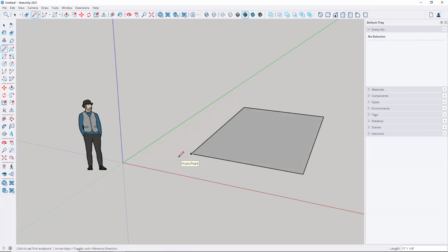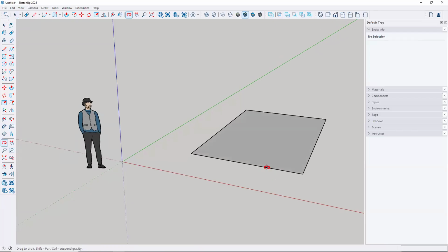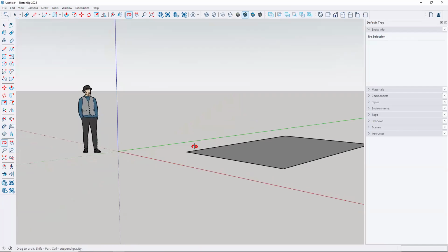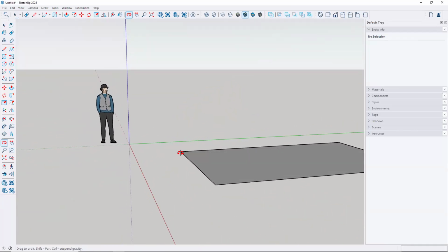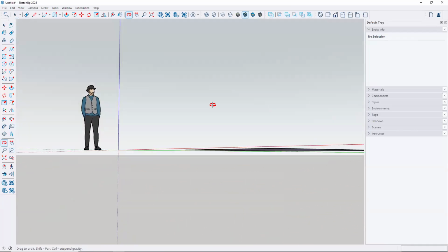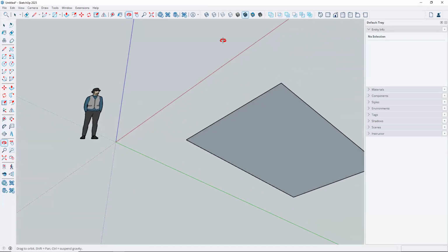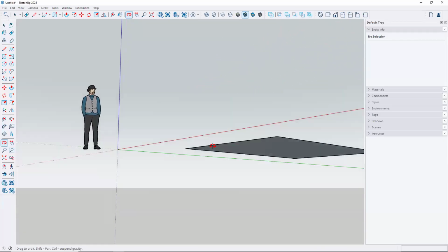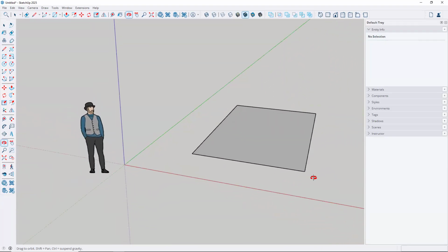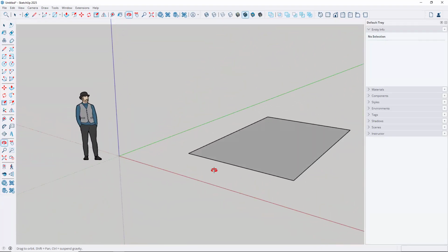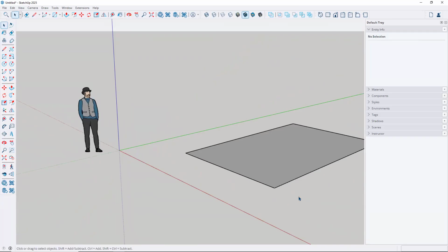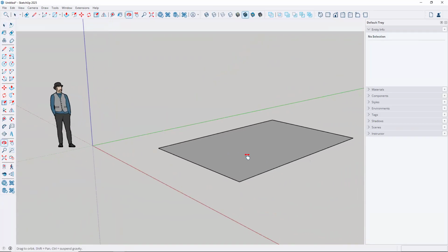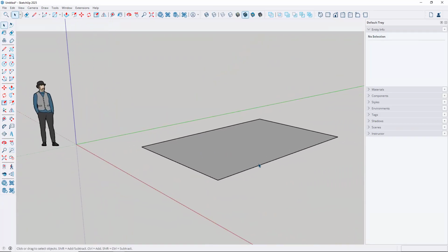And when I do that, go ahead and tap the space bar now, and you'll see that you have a surface. And now go ahead and orbit about that surface. And you'll see it's a dark gray, and you can even go underneath like this. So you are in 3D space now. And I'm just going to hold down my shift key and click and drag my wheel mouse so I can center this on the screen like that, and then continue.